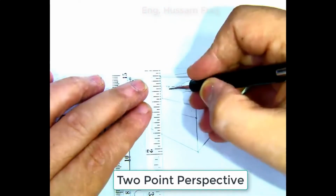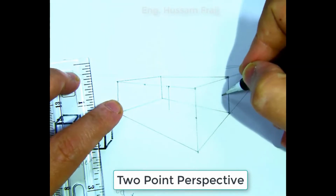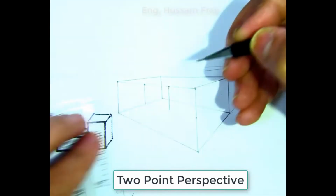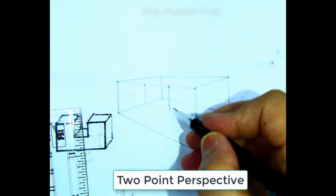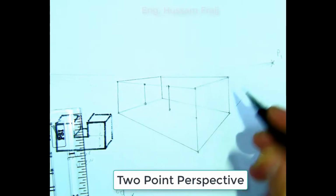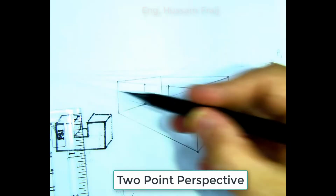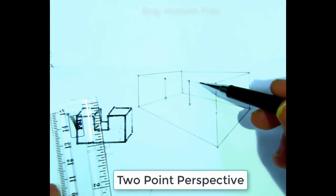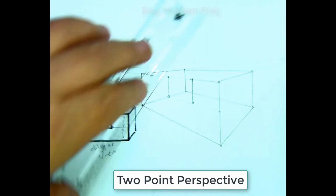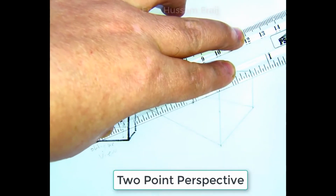like this. Okay, now from this point draw vertical, because in 2-point perspective the z-axis will remain vertical. Okay, like this. Now at each vertex, new vertex, new vertex, new vertex, you have to connect them to the right and to the left. They are already connected to the left. See, if you notice from here, they are already connected, but they need to be connected to the right. So I will do like this.